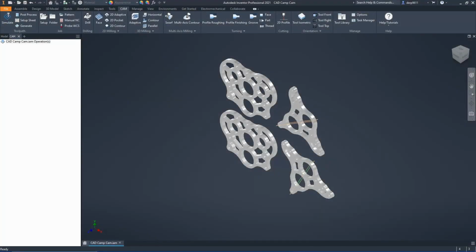A robot usually has 2 gearboxes, so here I've placed a total of 4 gearbox plates, 2 for each gearbox, and constrained them into a plane and moved them together so that they fit within a 12 by 12 square. After you create your assembly, you need to make a setup. To do that, click the Setup button.